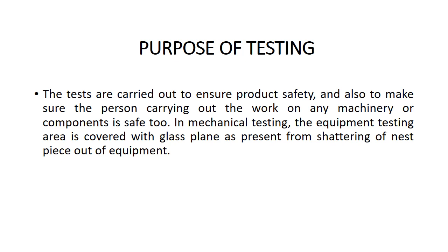Next one is impact testing or dynamic testing. When the given specimen is subject to a shock load, it is known as impact load testing or dynamic load testing. We have Charpy test, Izod test, drop ball test, drop dart test, instrumented puncture testing. Finally, cyclic. When the load is repeatedly varied in magnitude and direction, this test is called cyclic testing. The example of cyclic testing is a fatigue test.